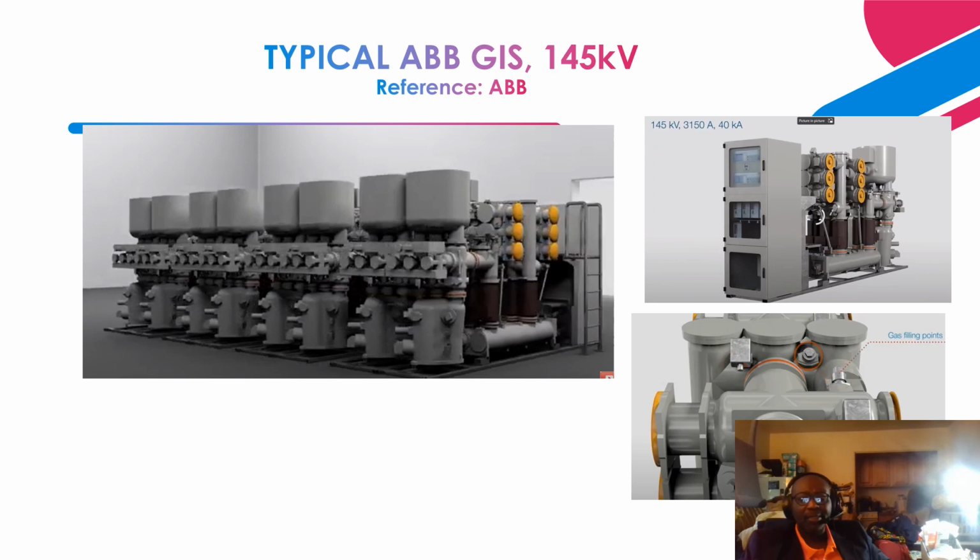As you can see over here, this one is the local control cabinet. Usually, it's LCC, right? This is where the control of this GIS all takes place. Inside this enclosure are the interfaces with other equipment. For instance, if the GIS is protecting the transformer, you have wiring coming from the transformer that comes in here, and also the interface to the SCADA.